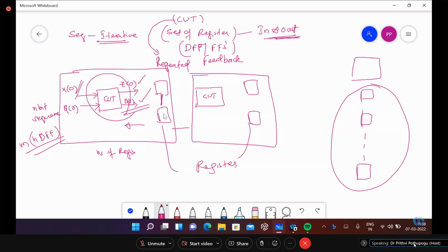If you need this testing response sent to the next stages, these act as the memory paths or memory segments. We scan the responses onto the registers, then update this status to the next stage inputs. Here we have the next set of external inputs, and we evaluate its response.